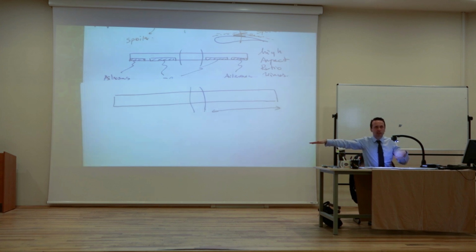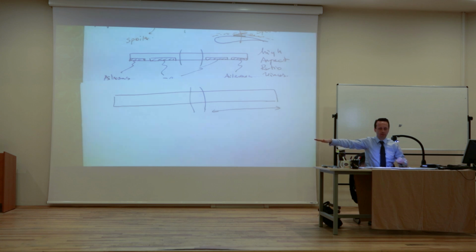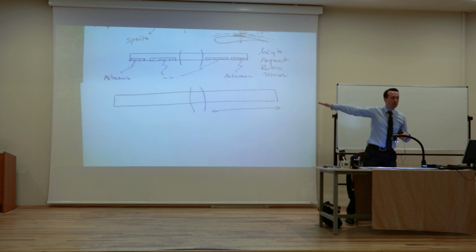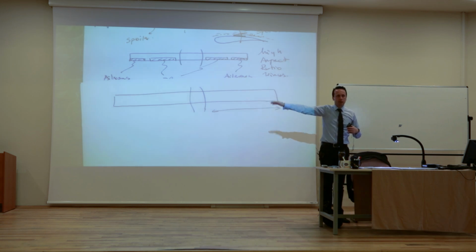Now, when the wing does that, it is interacting with the air, of course, and you're going forward. Imagine at the moment when the wing is going down, it increases the angle of attack, isn't it? So suddenly you have more lift, because of that movement. If the wing is not rigid and the airplane is oscillating because of the structure, now oscillation is not done by itself.